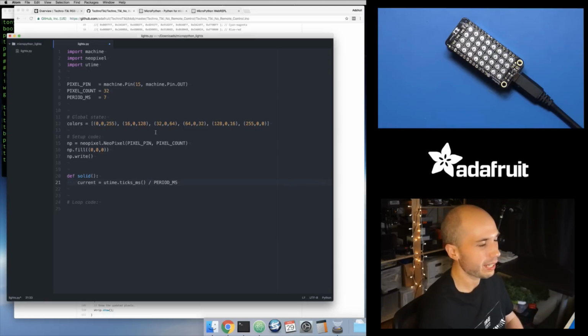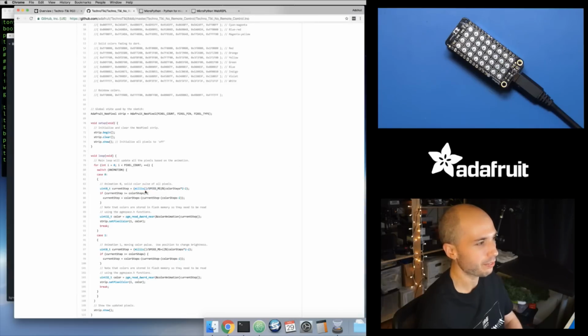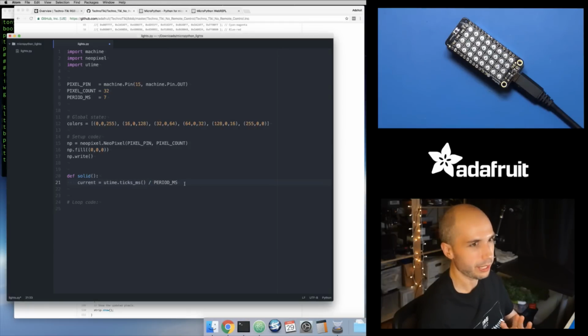Now the nice thing is, if you actually want to do integer division, which is the default in C in an Arduino. So when you see this divide right here, it's not necessarily the default. It's the default if both of your parameters are integers. And it just so happens that this millisecond function returns an integer and my speed ms value is also an integer. So this is going to do integer division. So I'll never get like a 1.5 or a 1.7 or some intermediate value. In those cases, it rounds down. So I just get 1 as the result back from this. And that's the behavior that I want in my MicroPython code. I want to do integer division.